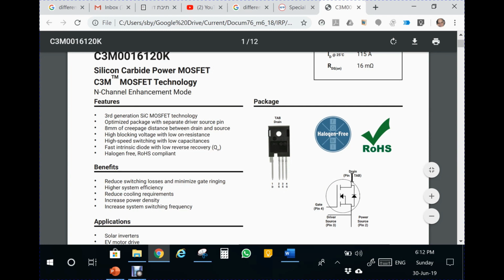Now we see here a device which has the MOSFET, the silicon carbide MOSFET, and a diode. This is a body diode. This is part of the structure here. This is not an external diode. In IGBTs, we do not have diodes, and if you have a diode in a package, it's actually an add-on.